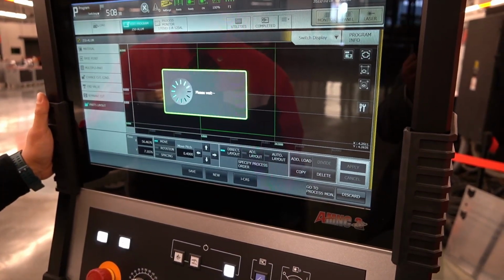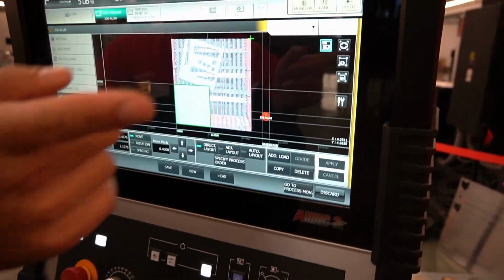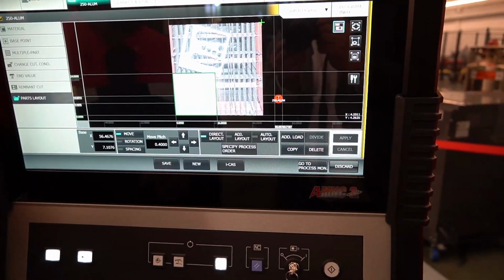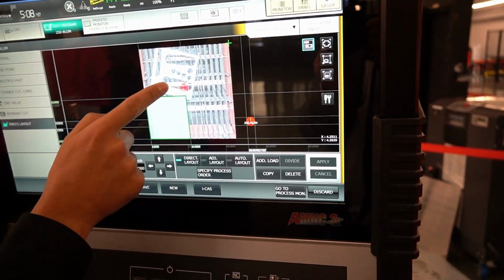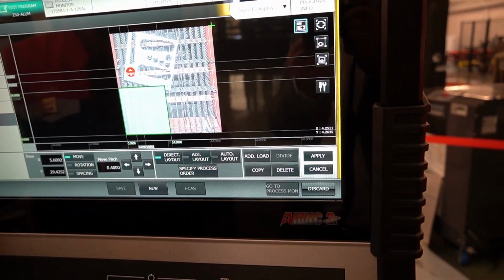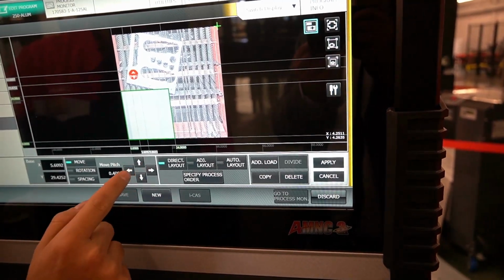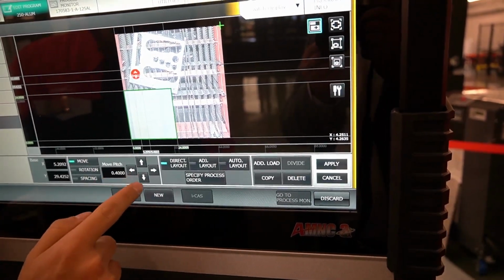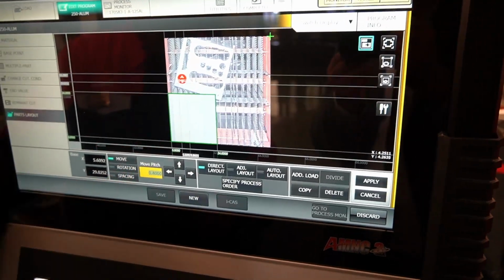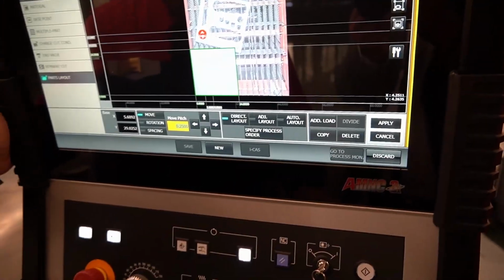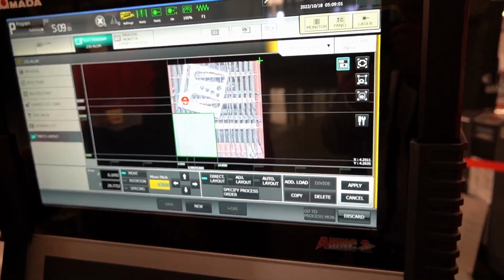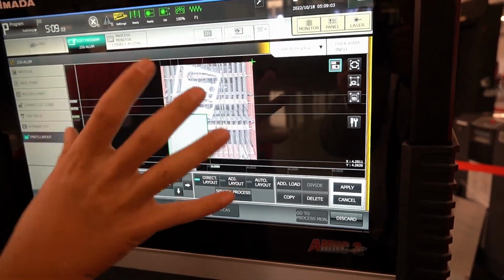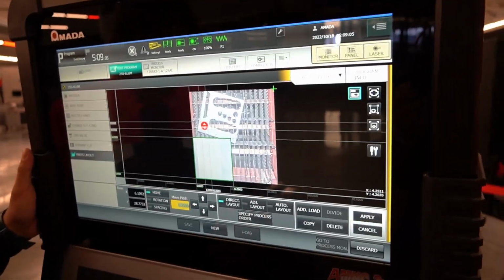So the Icast will take those parts, sheets that I've had inside the machine. And I can drag my little part here, and I can numerically change the position. I can add my pitch here. Let's go to 1/4 inch increments, so I can very precisely put it in a location. Some things really exactly.